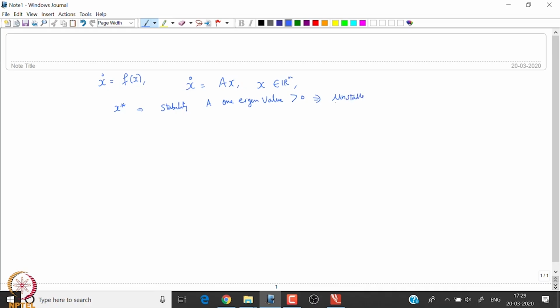Okay. Then it does not really matter if some of the eigenvalues lie on the origin, or say if I have a system like this which throws up a linearization this way, I do not really worry about what to do with these 0 eigenvalues, or maybe there is an eigenvalue here, because there is already an unstable eigenvalue here, right. So this is the sigma and the j omega axis. Okay. So we will rule out these cases where the linearization throws up a natural instability in terms of an eigenvalue in the right half plane.